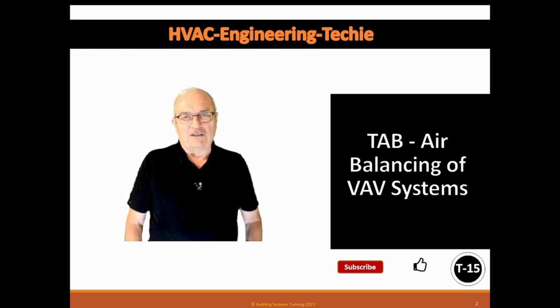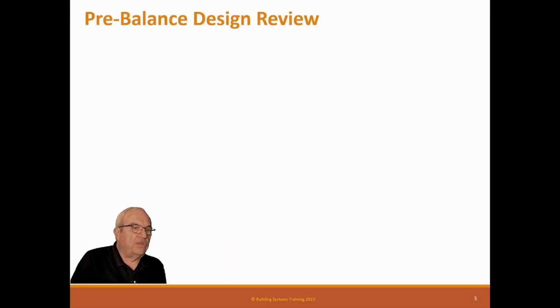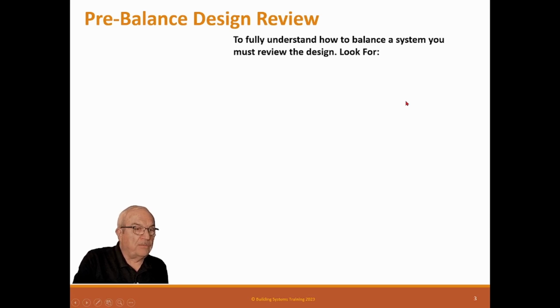So let's get started on VAV systems. The first thing we need to do is the pre-balance work that we do before we get on the site. And we need to do a pre-balance design review. The reason we want to do this is because we want to make sure if we see any problems in the design, we'll know what to do when we get on the site.